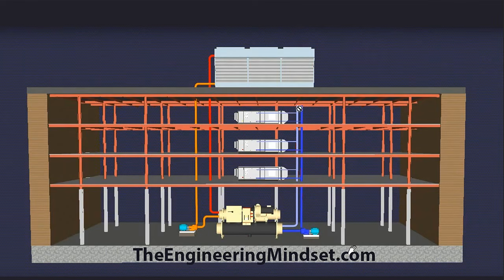and that's distributed around the office. So that water there, that warm air which is returned, enters into here, gives up its heat, so it transfers the warm air, the heat from that, into the coil of cold water, and the cold water gives off its coolth into the air, so it comes out cold air here, and that obviously raises the temperature of that water, and that then returns it back to this riser into the evaporator of the chiller, where it then gives off its heat into the condenser side of the chiller.